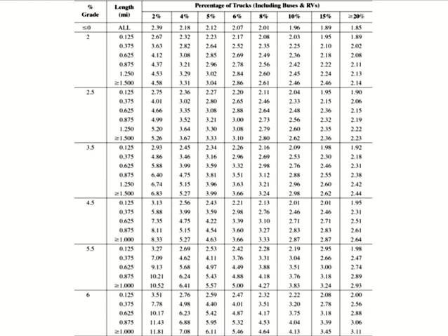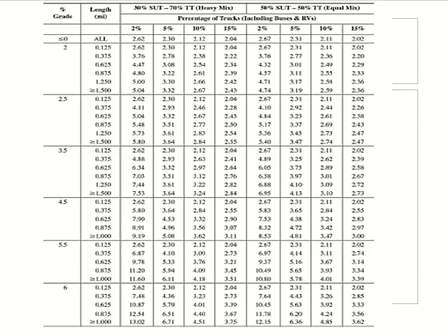Single unit trucks are more. But single unit trucks can be equal to trailers, or they can be less than trailers. If you have any of these conditions, then you will use this table. So this table is for the rest of the conditions, if they are equal or the trailers are more. Half of the table, this half, is when trailers are more, and this half when they are equal. Clear? And again you need the same things: gradient, length of gradient, and percentage of heavy vehicles.